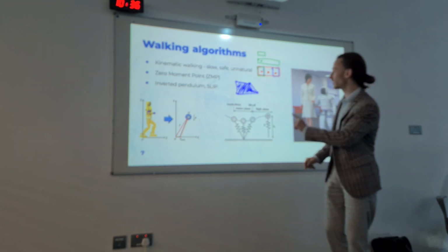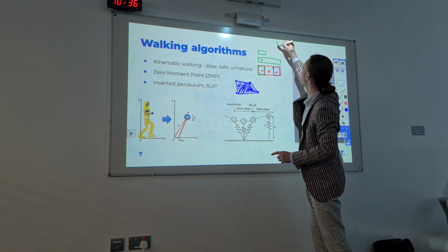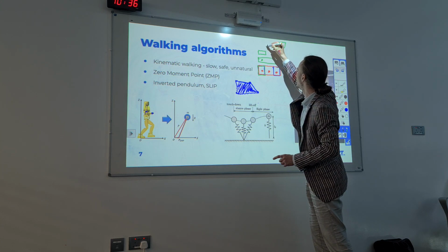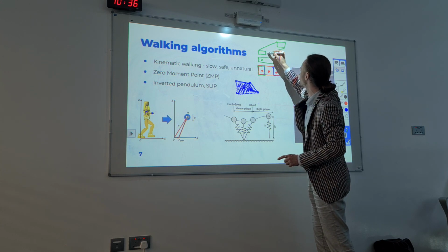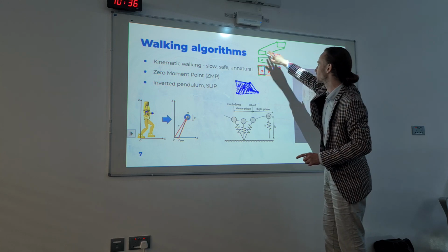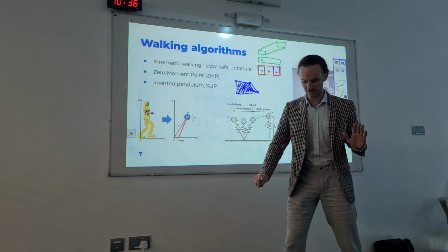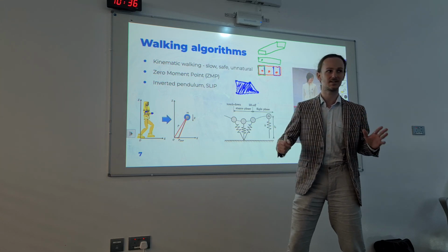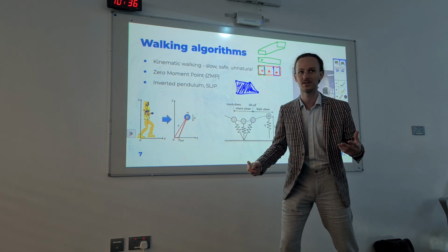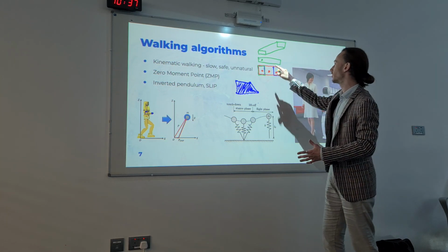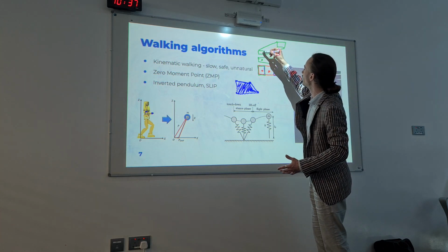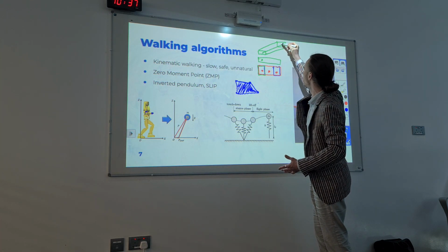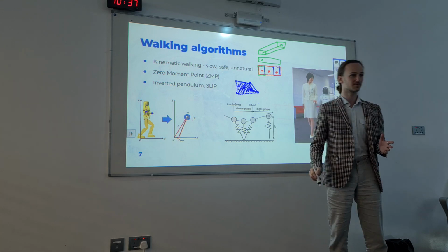And then, the important thing, the support polygon becomes this one. So this is the left leg, this is the right leg, and the support polygon is now like this. Why is that? Because I can move the center of mass from one leg to another statically, pseudo-statically. So the support polygon is like this, and we move the center of mass here, and then repeat the procedure.